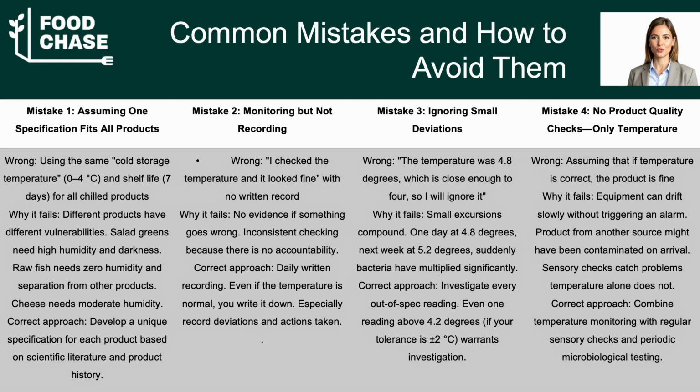Let me highlight 4 common mistakes I see in food facilities. First, one-size-fits-all specifications. I walk into a cold room and ask, "What is your storage temperature?" And they say, 4 degrees for everything. But salads are different from fish, which is different from cheese. Each needs tailored conditions. Second, monitoring without recording.